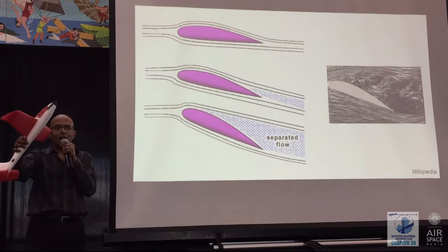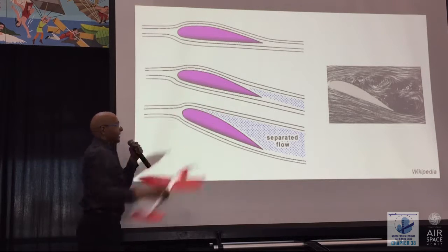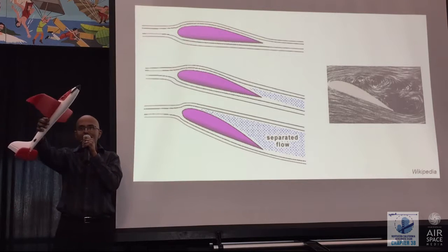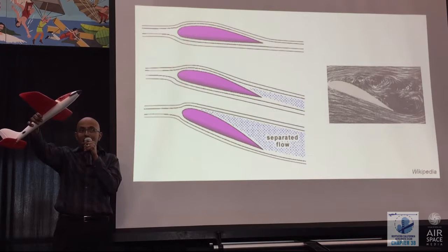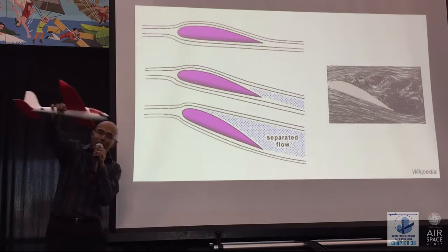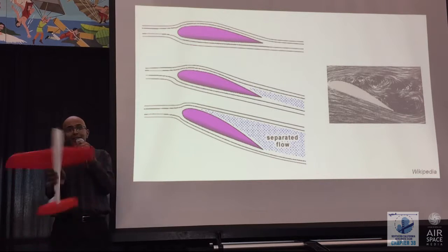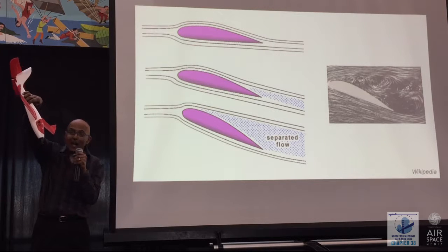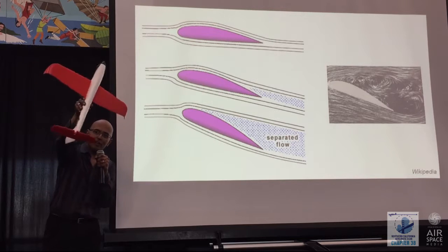At some point, when that angle of attack becomes high enough, the air will refuse to bend. It just doesn't want to follow the wing anymore. What happens then differs between airplanes, but in many airplanes, it's kind of a sudden thing, and the airplane sort of falls down and drops. So that is kind of dramatic, but we learn how to recover from that, right? Put the nose back down, add power, get the airplane under control, don't have the elevator fall off.